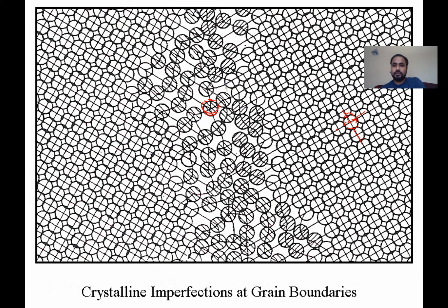And when you do different kind of heat treatment, you can actually change the grain size. So if you want something stronger, in general, small grain size is something which is desirable. So when you do casting, and for this project, I think we are supposed to do casting, the grains come out to be really big. So if you control the parameters slightly better, you might be able to reduce the grain size. That will help you to get a much better hammer out of whatever material you are working with.